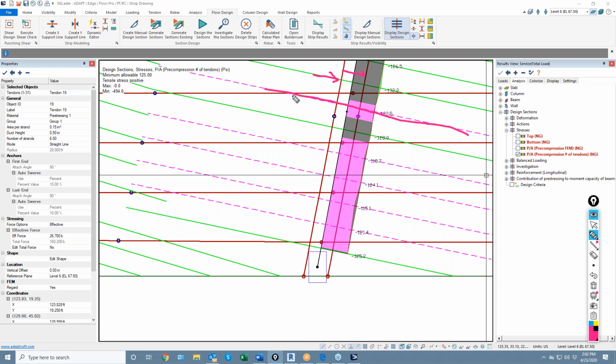But you also have a little bit of force from this cable that intersects it at some very shallow angle. So any tendon that intersects that section, there is an initialization range where if the tendon, I think, is less than 30 degrees, it would not consider the cable. I'd have to go back and check that, but some of these cables may be considered based on their orientation relative to these design cuts.